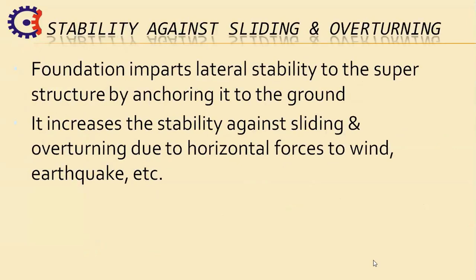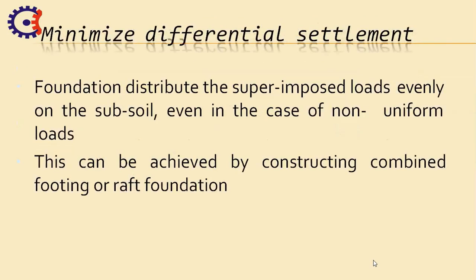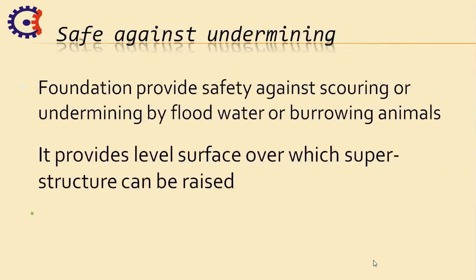The next is the stability. As we discussed earlier, foundation imparts lateral stability to the structure by anchoring into the ground, increasing the stability against sliding and overturning due to horizontal forces from wind, earthquakes, tornadoes, imposed loads, live loads, etc. Then minimize the differential settlement. Foundation distributes the superimposed loads evenly on the subsoil, even with non-uniform load. This can be achieved by constructing a combined footing or a raft foundation.